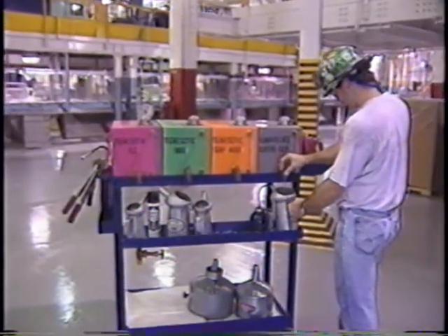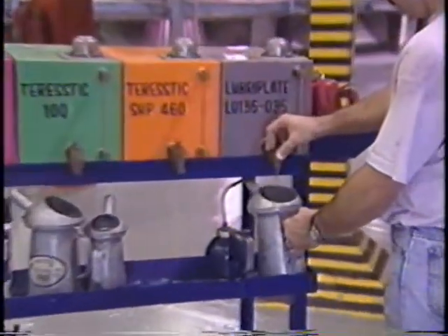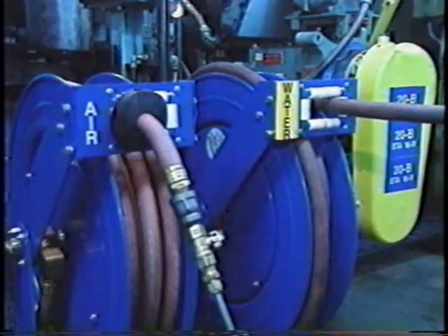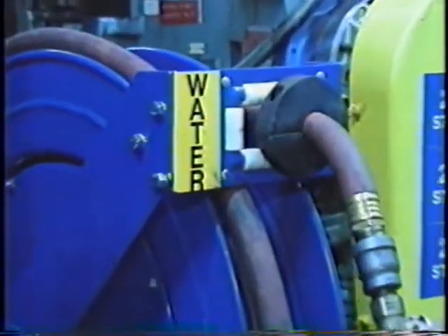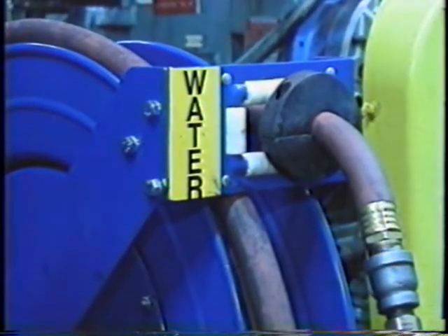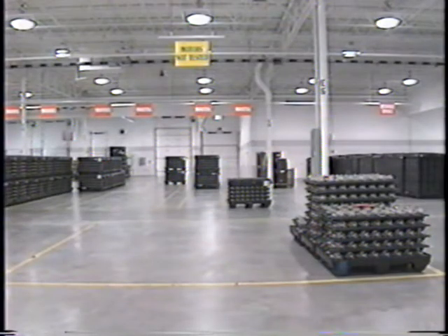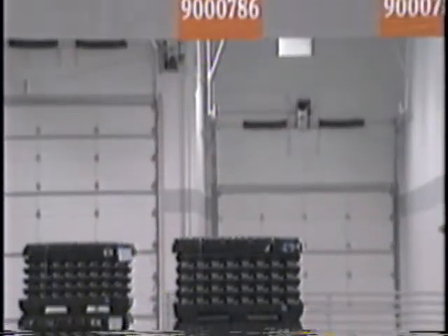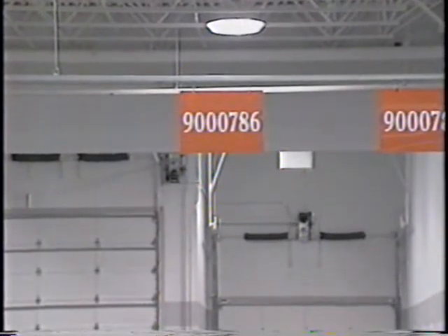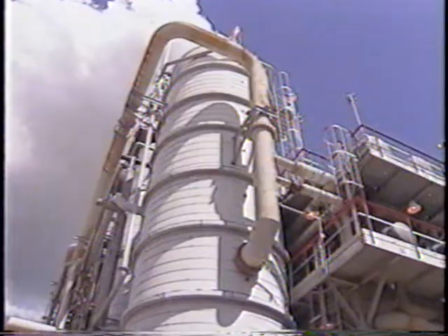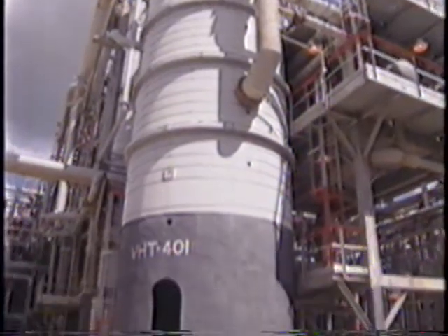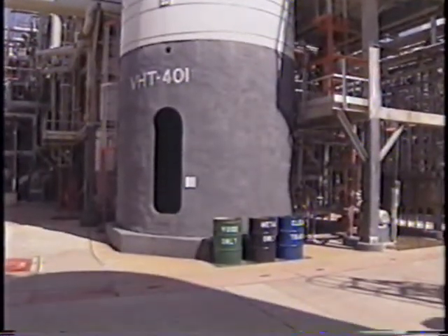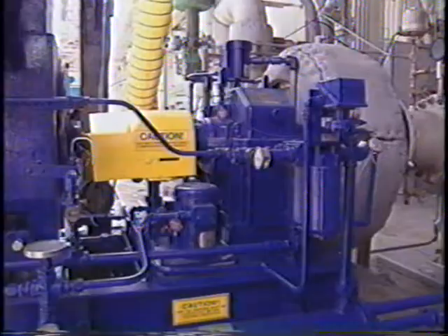Color coding is another effective visual technique. For example, color coding hoses to show what flows through them is critical for safety as well as efficiency. Color-coded signboards help people find their way around the workplace more easily. Be sure to standardize the use of color codes in the factory so everyone uses the same codes. Since some people are colorblind, always back up color codes with written labels.